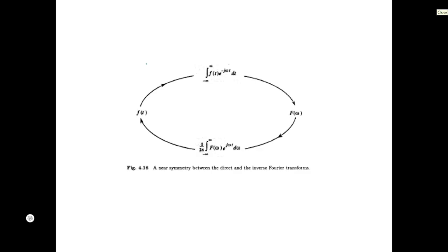Okay, by the Pan-Tompkins algorithm, we acquire the ECG signals. Then after getting the ECG signal, we have to apply a band pass filter, which will allow us to extract the QRS complex, and herein the band pass filter has a cutoff frequency of approximately 16 to 22 hertz. So it will allow you to extract the QRS complex frequency components, and by analyzing that you can find out the heart rate in the ECG signal that has been given to you.